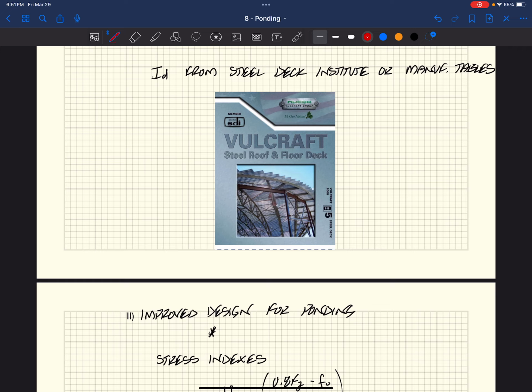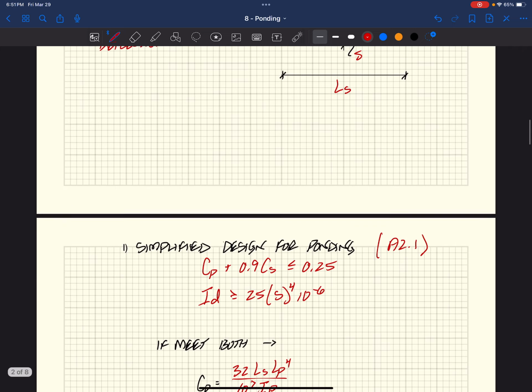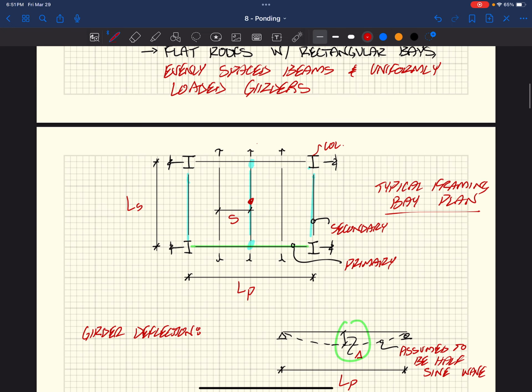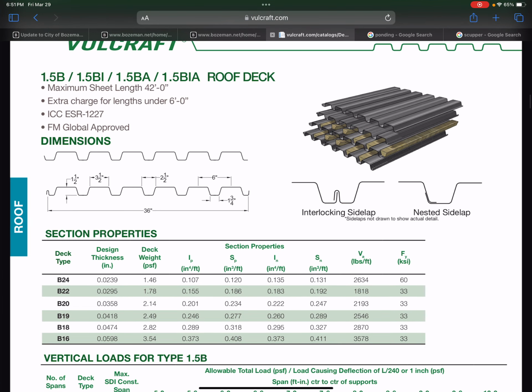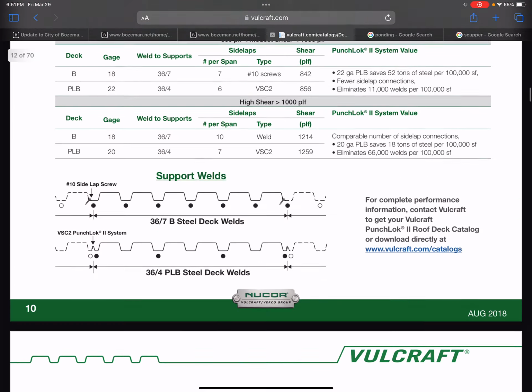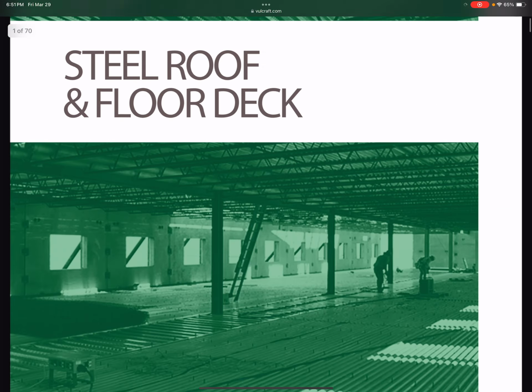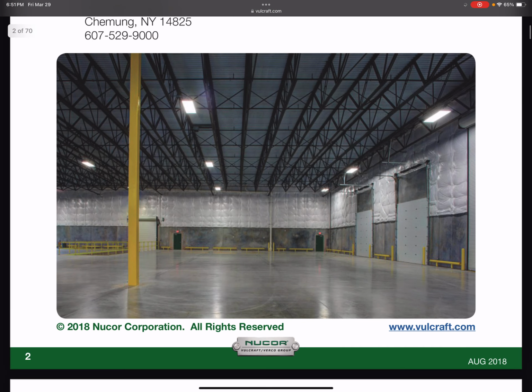One other thing, this is a typical bay, right? We have secondary members attached or supported by primary members, which then are supported by columns. But sometimes that's not always the case, right? We're going to have to use some engineering judgment here, or our own means of analysis, to come up with a solution for some cases. Like I think it's in this one right here. There may be a girder where this yellow column is. There may be a girder spanning right to left, which there probably is. But out there on the exterior wall, there isn't, right?